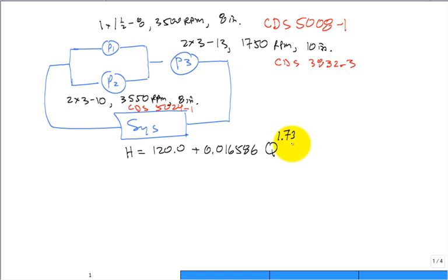The units work such that you feed it GPM for the flow rate, and it returns foot head loss in the system. Somebody says, I'd like to work with energy head rather than elevation head. It's going to be exactly the same, in units of foot pound force per pound mass, numerically the same. But we're going to work just in feet.